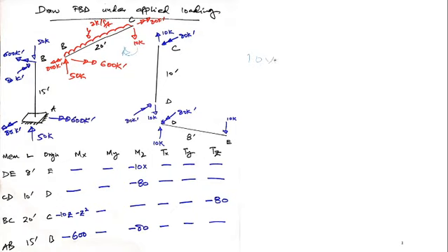So 10 into 20. From upwards, this is Y, this member is in Z direction, so there would be a moment in X direction. The magnitude of that moment would be equal to 2 into 20 into 10. If you solve it, you will get 600 kip foot. So I have applied it.